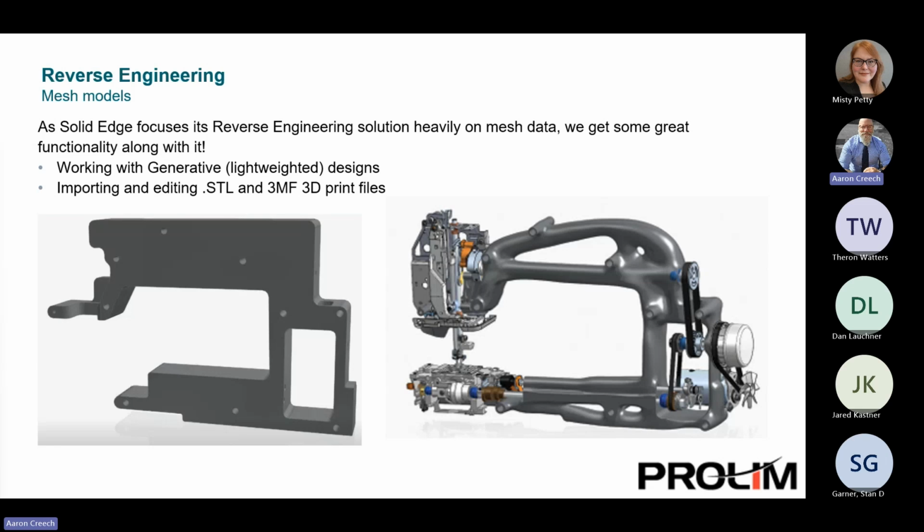And so based on your parameters, a specific component material, a design space, or an envelope, and permissible loads and constraints, Solid Edge will compute a reduced mass geometrical solution that maintains the structural integrity. So not only is this a smaller, lighter part, it also has better airflow, and it is a lot less weight, so a lot less material. So probably a cheaper part, and much easier to manufacture with 3D additive manufacturing.